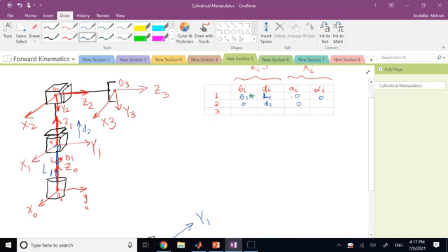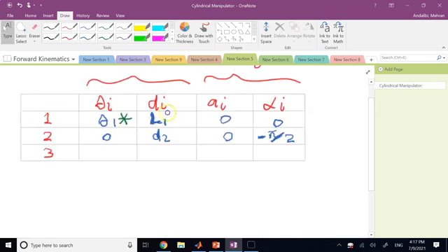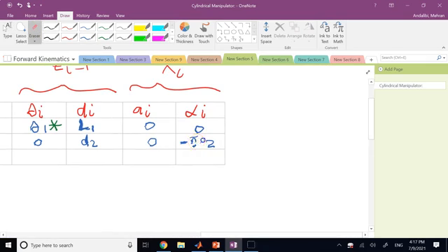Now, do you need to twist about X2 to align Z1 and Z2? Yes. If you see here, this is your Z1, this is your Z2, and this is your X2. They are not aligned. What you need is to rotate about this X2 a 90-degree angle to bring Z1 on the top of Z2. And since X2 positive rotation is counterclockwise and this rotation is clockwise, so yes, you need a twist of negative pi over 2. You get negative 90 degrees to make the Z's align. So that is very important that we recognize it, that there is a twist involved.